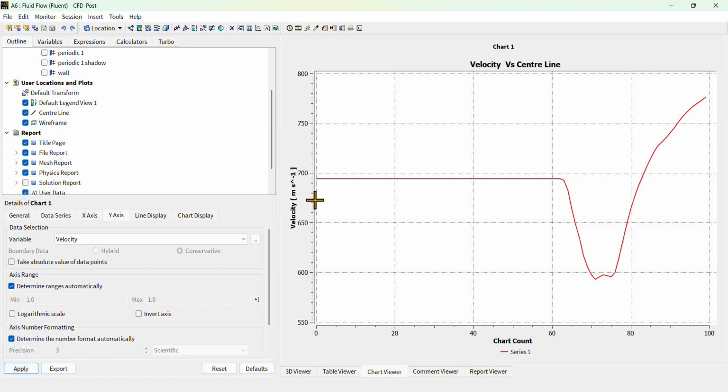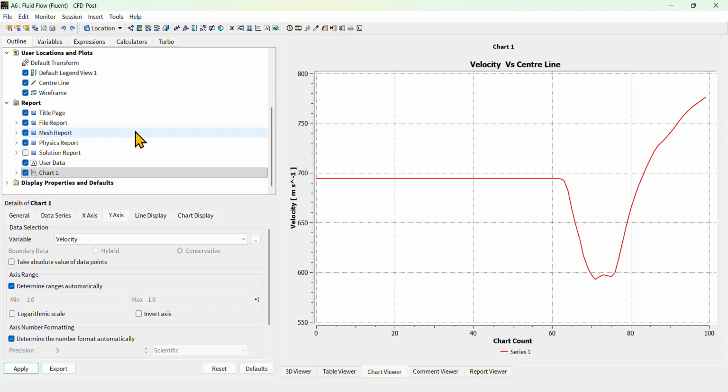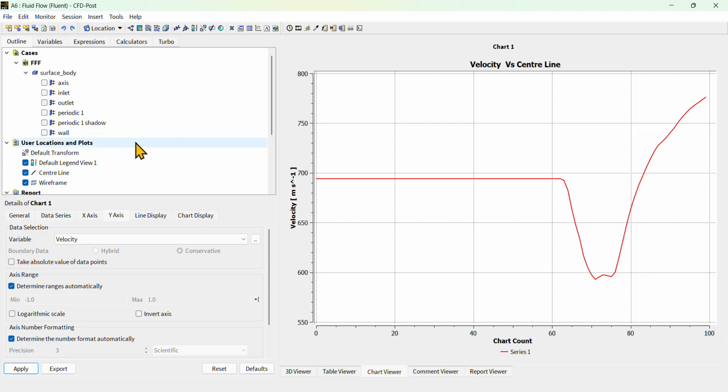You can see this is your velocity contour. So the velocity is maintained constant before the mixed supersonic intake system. Here, the velocity decreases, and at some portion at the inlet, it is increasing. So we try to avoid this increase by changing the inlet and exit pressure of the mixed supersonic intake system. Okay, this is how we can plot our x and y velocity. Okay, with this, we finish the modeling and analysis of the mixed supersonic intake system of a ramjet engine. Okay, thank you.